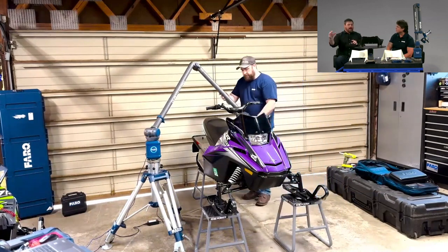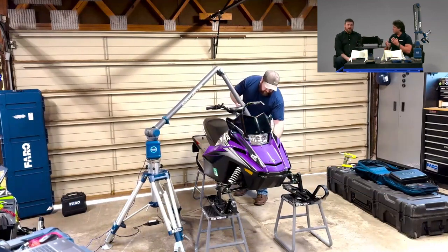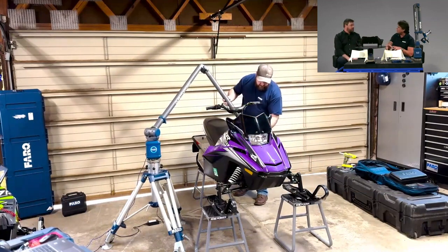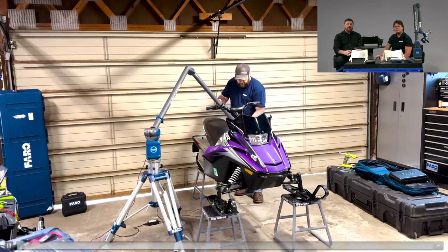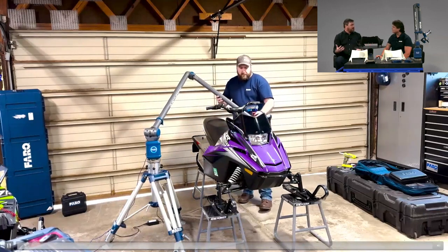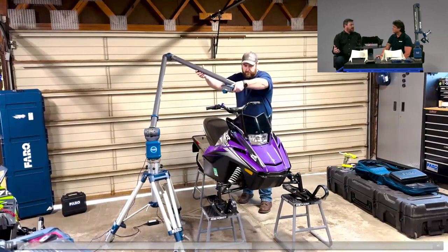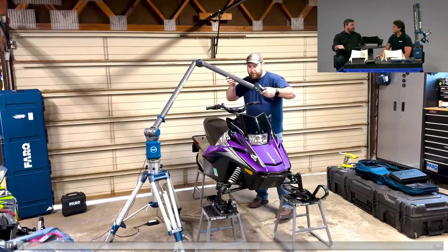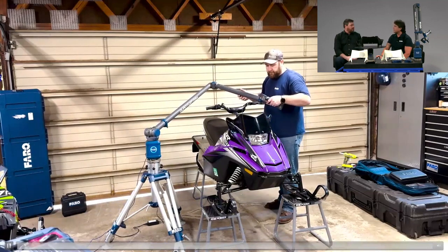That way you can hide and show and turn on and off different things, and check interference and problems before they happen in the real world. Exactly. And if I design a new part directly on top of the part, you have the entire sled that you could run analysis on, CFD analysis and things like that, with the entire scan data set. You can actually check clearances of the steering wheel, all of that is possible if you scan the entire thing.